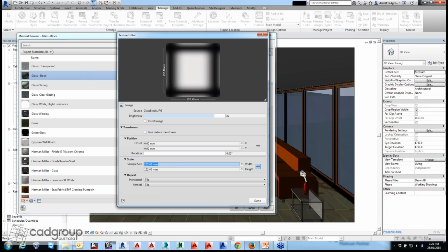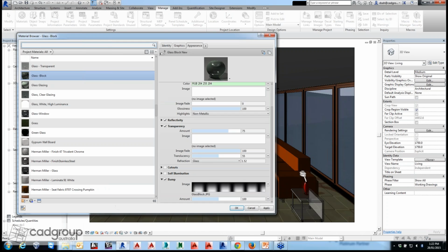Now I will try to use this so that we have a nice wave effect on the glass, and I will resize it based on the height and width of that glass. So I'm going to remove that and say width is going to be 700 millimeters. The height is around 2400, which slightly matches this particular size. Now we can have this preview in different views.